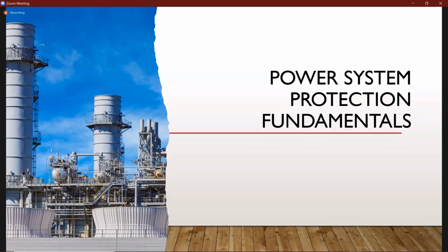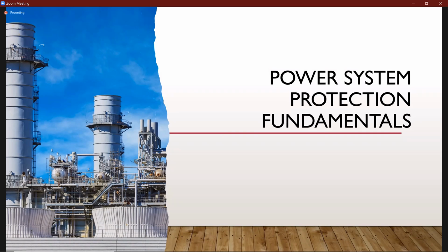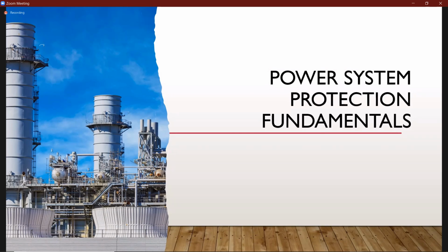However, I noted that almost the entire class went ahead and did studies on the entire system, especially for the first section where we were finding where you conducted a 3-phase fault, 50% along the Duhaney to Washington Boulevard line.